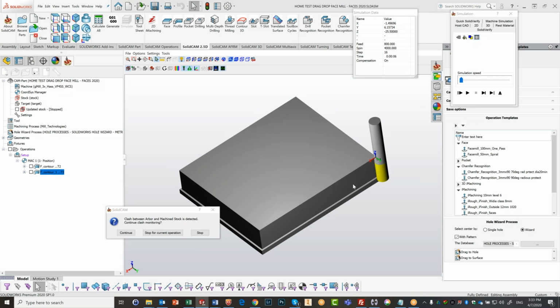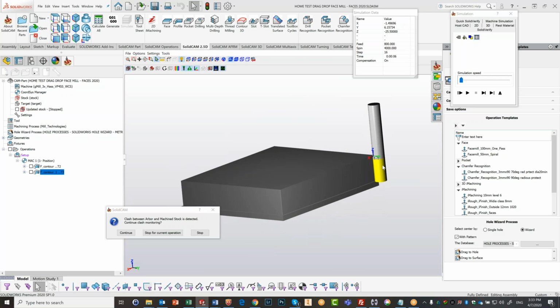Okay, don't all answer at once. Go ahead. Because the reference is not big like the material. Okay, because the cutting length of the tool is more than the material. My cutting length was 24 millimeters, but I'm going down 25.5 millimeters. And I also still have material that I didn't take off with my face mill on top.